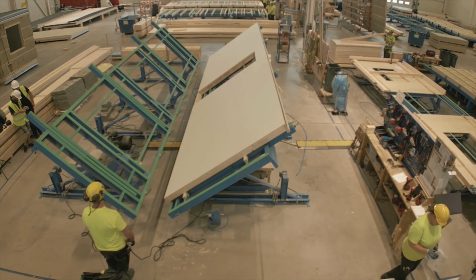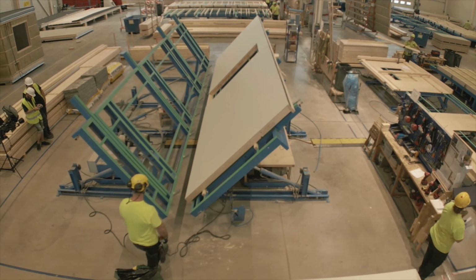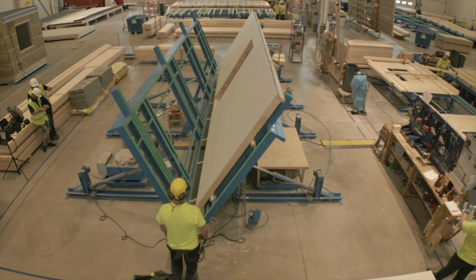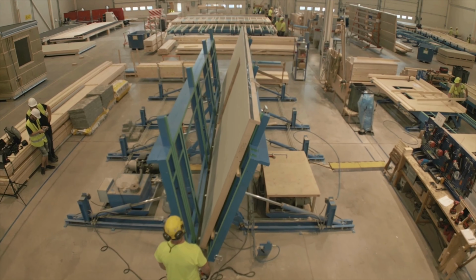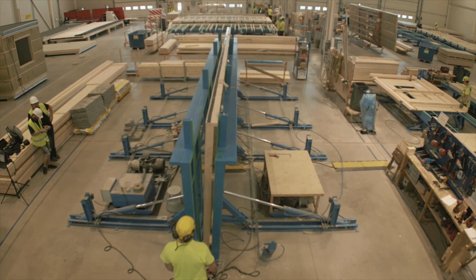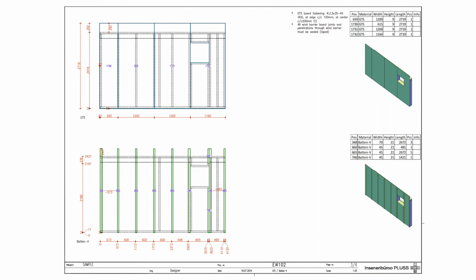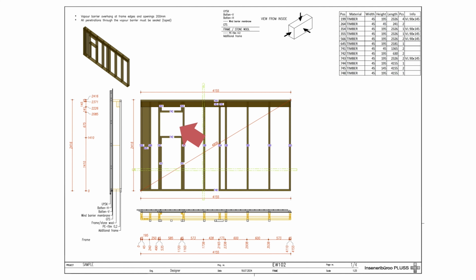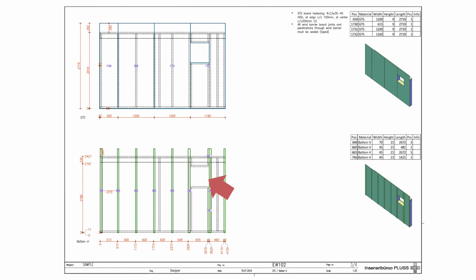When the worker has finished installing the additional frame as the last layer of the inner side of the wall, the element should be flipped around, as external layers need to be added too. This is also the reason why on pages 3 and 4, when describing the board and batten installation, the 3D view sides are not included as they were indicated on the first pages. Note that when flipping the element over on the work surface, the window location has shifted to the right side.